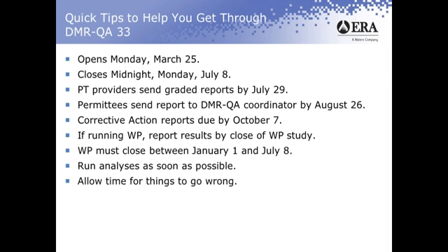Because most of you are wastewater treatment facilities, things can happen in your facility. You could have a bad rainstorm, things could flood, something could happen with a chemical spill, and all of a sudden you're forced to address that as opposed to being able to address your DMR QA standards. So again, I want to reiterate the importance of allowing time for things to go wrong. You have roughly 110 days to conduct your DMR QA analysis.